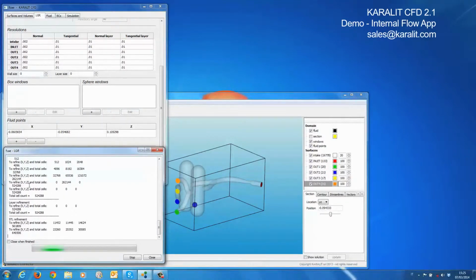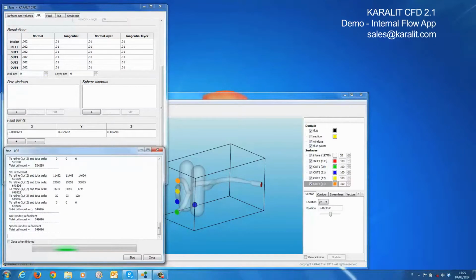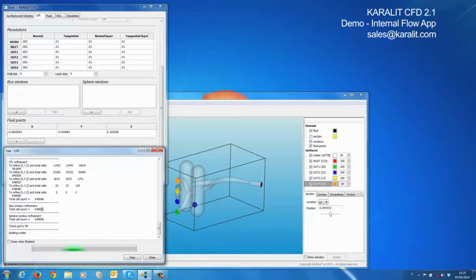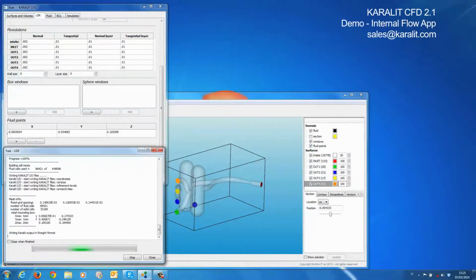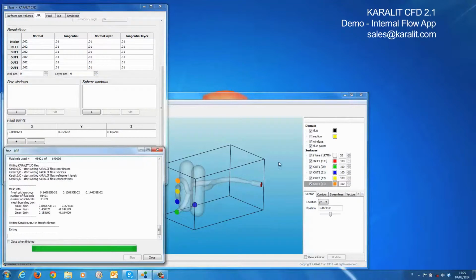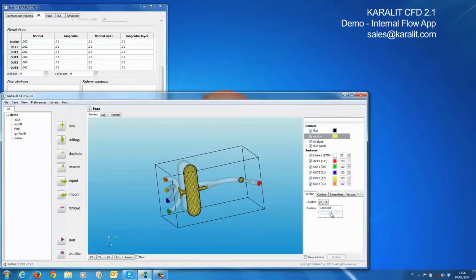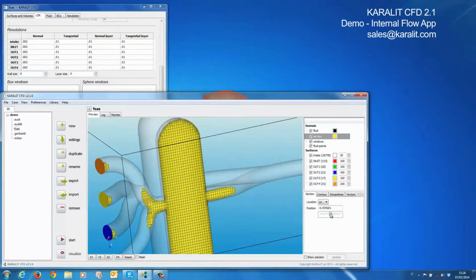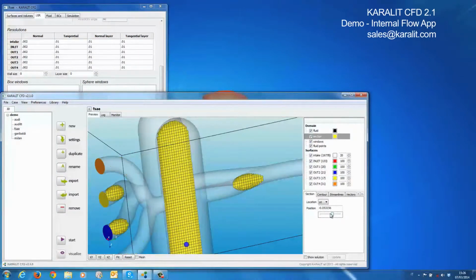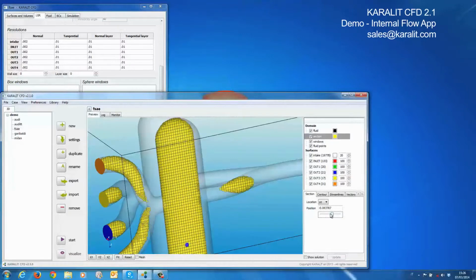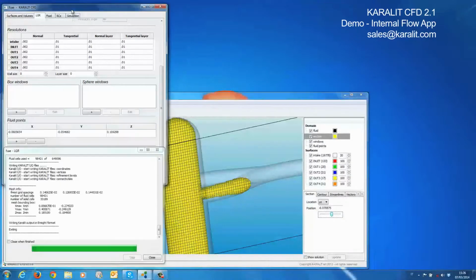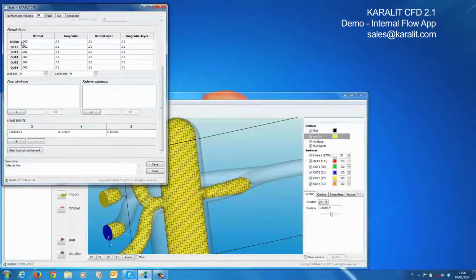You know, there are all the processes done here in the background, the refinement and the surfaces. There is the selection of the cells and the boundary cells, and basically the meshing process is done. So I can see here the resolution near the wall. I can of course improve it, I can do a finer mesh at the wall, I can do whatever I like. So this is basically what happened. Now I'm done with the mesh. I'm closing the mesh process and going to the fluid.